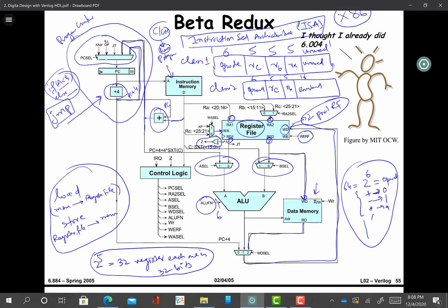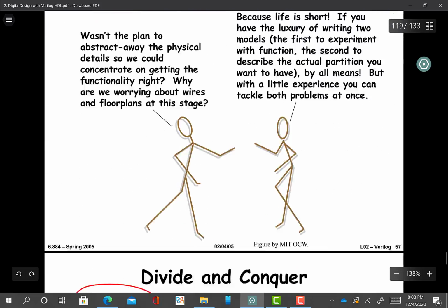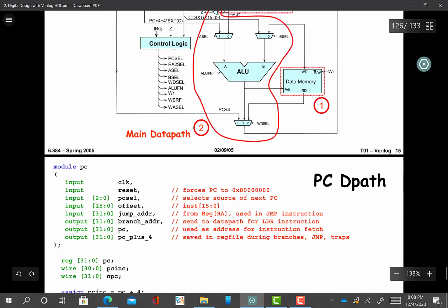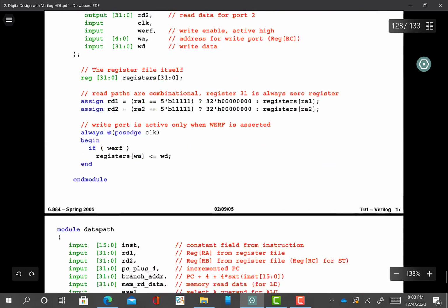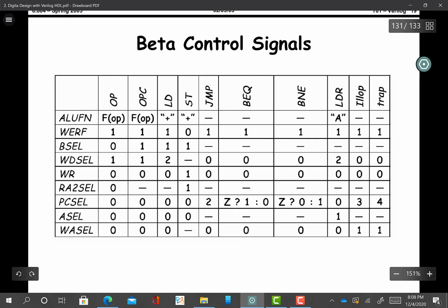So these are some of the signals, some of the logic that I discussed, and this is the FSM, which has different signals generating all the muxes. The logic for the control, or the control FSMs, depends on the instruction set architecture. But let me directly take you to the control table, which is somewhere down here. Again, sorry for the unarranged slide numbers. They are not serially arranged. So these are the control signals, or our FSM. This is the FSM table.